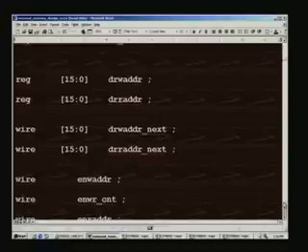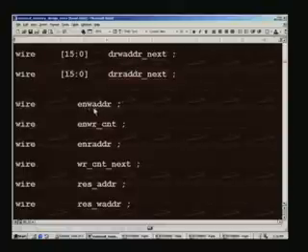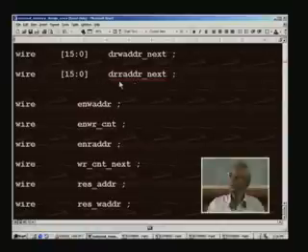And similarly, there will be one for address write, there will be one enable signal used internally, and also since we are using external RAM, we will not be in a position to achieve the high speed that we can with the on chip RAM. For example, you may have to scale it down by a factor of 2. For instance, if you are operating the system clock at 100 megahertz, we can access external memory only at a 50 megahertz rate. So, in order to do this, we have a counter here. The counters are separate for read as well as write.